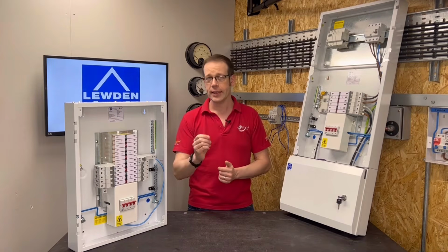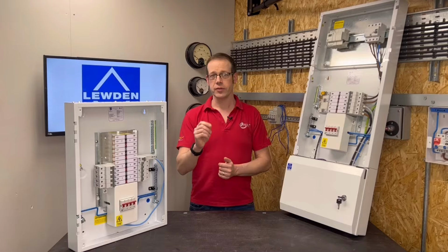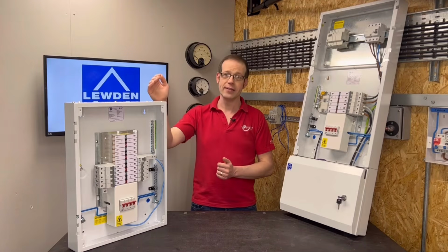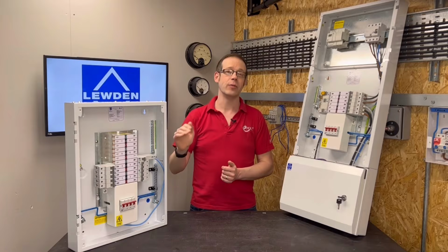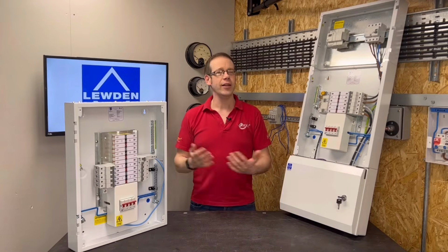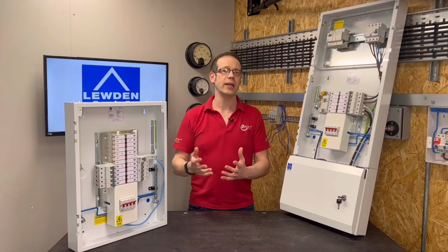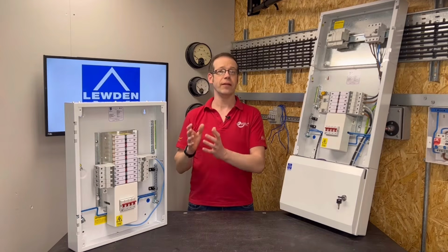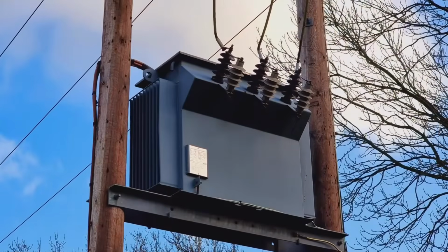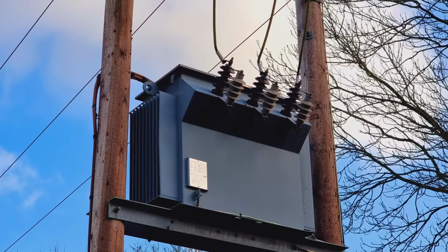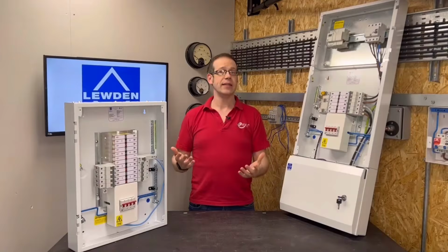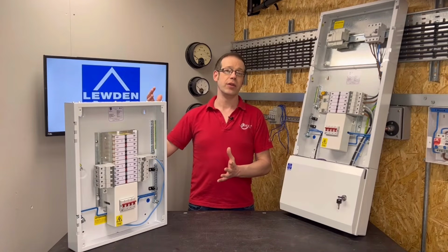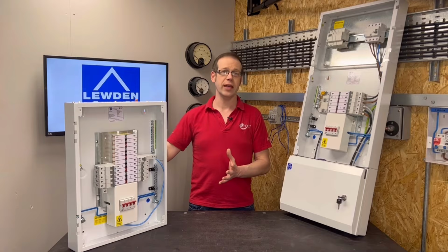A better way is to generate at a manageable voltage, then step it up to a much higher value for transmitting long distances, and then stepping it down when it gets to where it's going to be used. In the early years of electricity transmission, doing this to DC was a bit tricky and inefficient, but it was found to be quite straightforward and efficient to do it to AC using relatively simple bits of kit called transformers. So we started using AC because it was an efficient way to transmit electricity long distances while giving us usable, manageable voltages where it gets used.